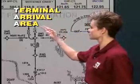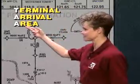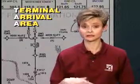The key to this approach is that it utilizes a concept the FAA calls Terminal Arrival Areas, or TAAs. When you have the capability of going directly to any point on the globe while you're IFR in the clouds, you need something to tell you how high to be so that you don't hit anything that's attached to the Earth. And that's where the TAA comes in. A TAA divides up the world in the vicinity of an RNAV approach into 3 areas and gives you a minimum altitude to use while going through each area. It's so simple that even I can understand it.